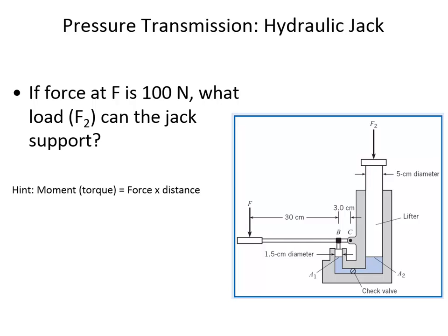What if the pressure here is 6,225,000 pascals, and then what if it was oil all the way up here and it was like 1 meter higher? A meter's a lot, so 3 feet. What if there was a 3-foot deflection? So the delta P for 1 meter is going to be delta H times the unit weight of the oil. Well, we don't know what kind of oil this is, but since it's oil, it won't be more dense than water.